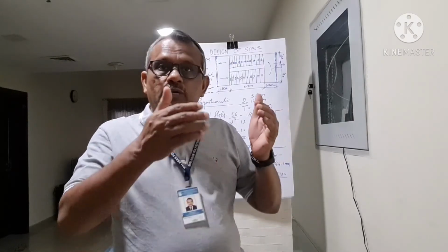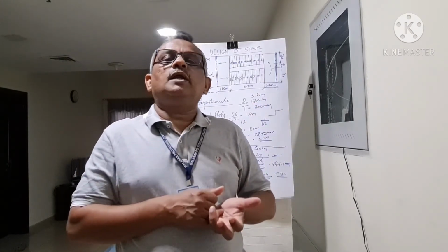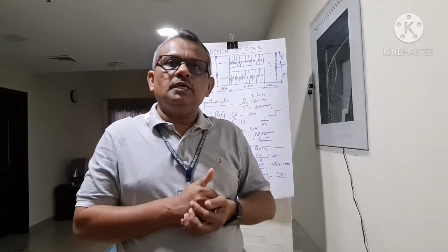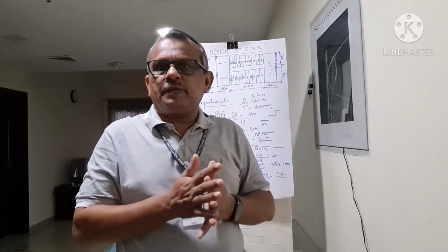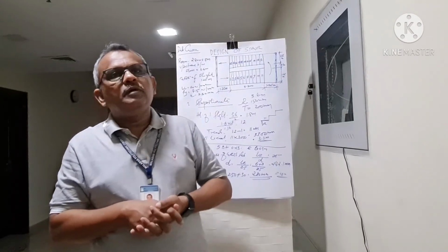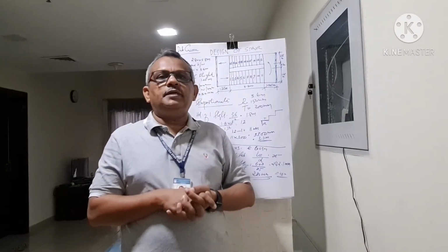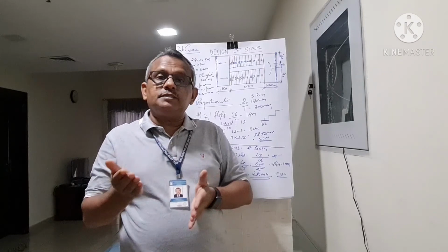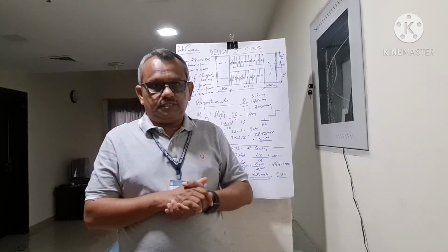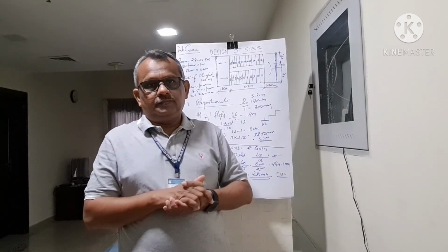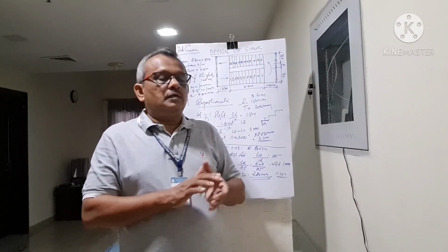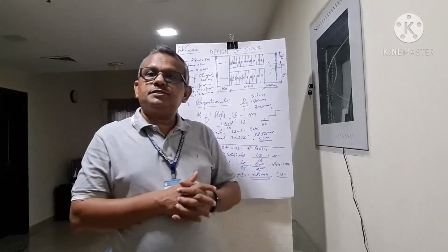After this, we have to analyze the loads now. What are the loads? Dead load, live load and floor finish. Calculate the three loads, add together to get the total load and multiply with the partial safety factor to get WU, and once we get the value of WU, find out the bending moment, WL squared by 8, and after that, design the steel reinforcement Ast and distribution steel. That process, those steps, we'll do in the next video from step 4 onwards, right?